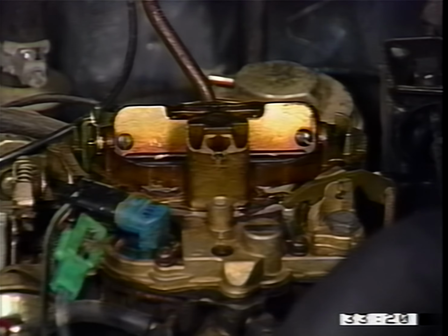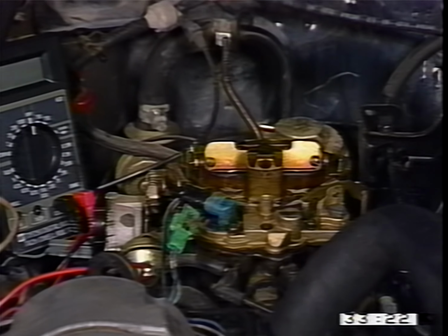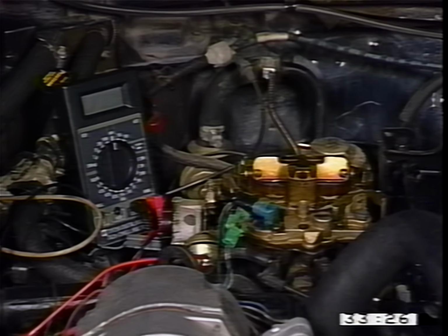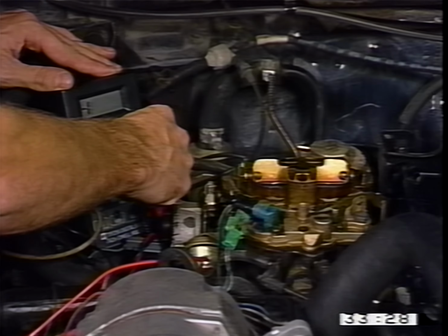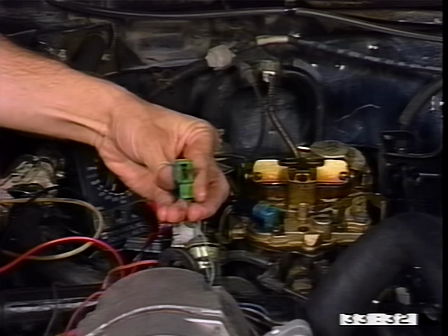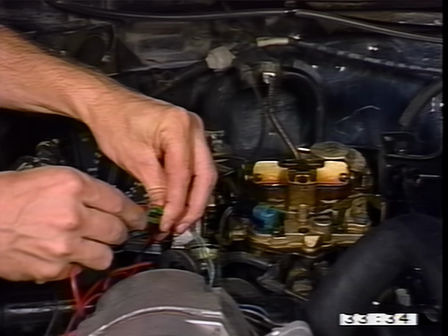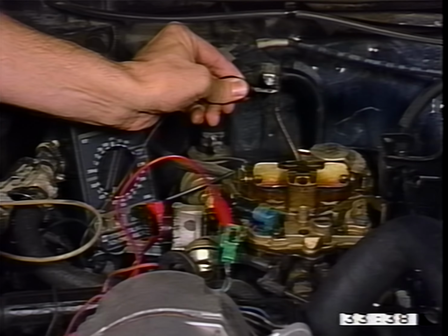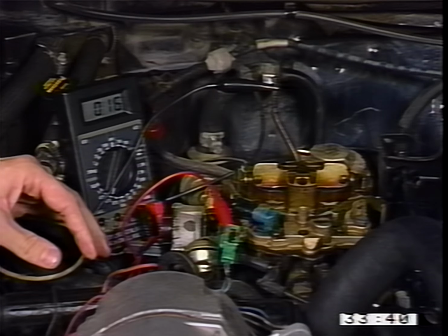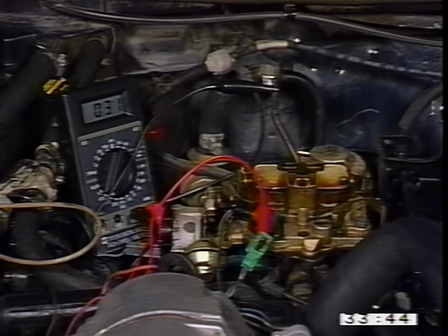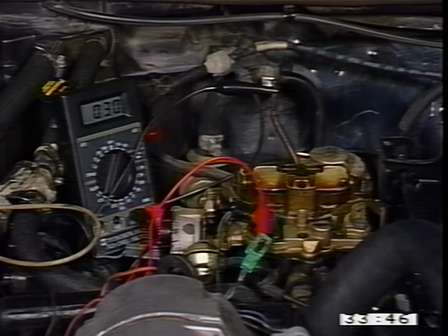A dwell reading on C3 carbureted models indicates if the mixture control solenoid is working and if the fuel mixture is rich or lean. The dwell meter is set on the 6-cylinder scale, no matter the number of engine cylinders. Connect the dwell meter to the green connector you'll find near the carburetor. The connector will not be connected to any circuit except when testing with the dwell meter. Keep the terminal wire away from all grounding sources, including rubber hoses.